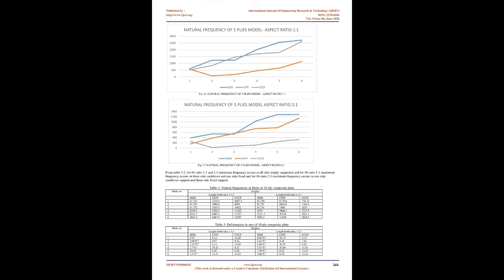On the other hand, composite material can have a widely varying set of material properties based on the chosen fibers, matrix, and manufacturing process. This makes modeling composites complex and often a mix between materials with widely differing properties. The most difficult is that damage in composite material often occurs below the surface, which further prevents the implementation of several detection methods.